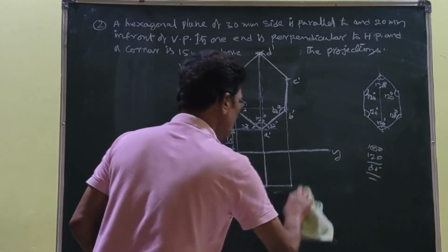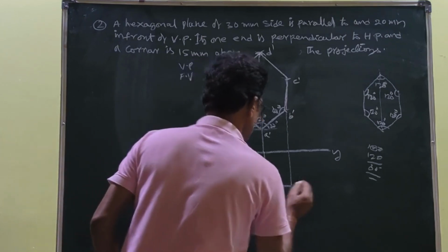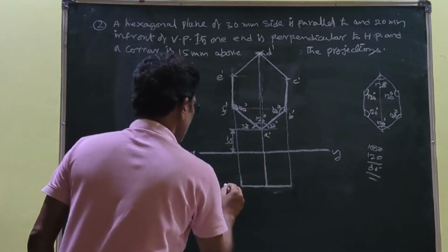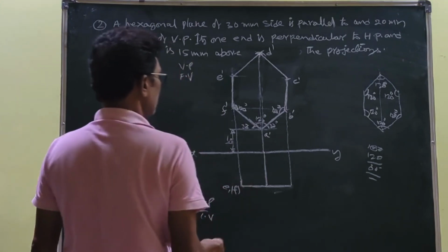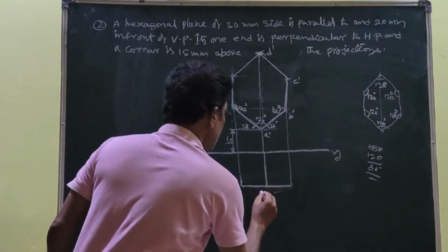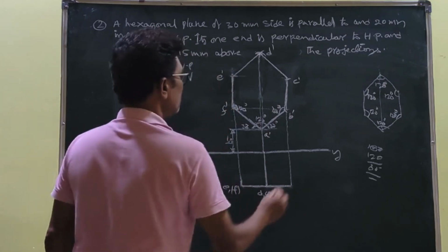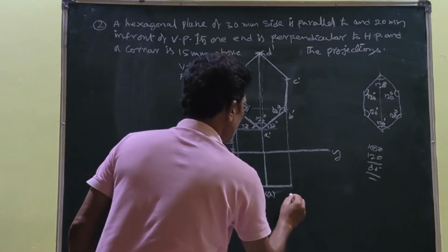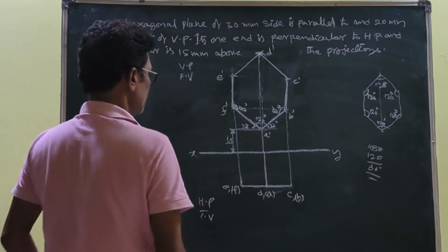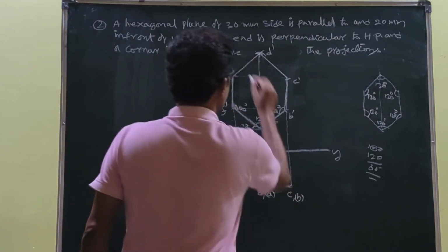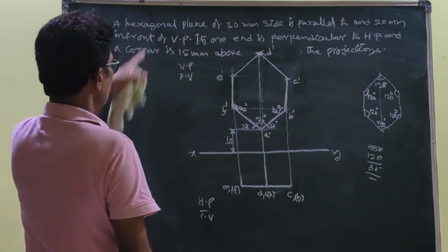So you can remove this one. This is the top view. Now the names. This is the visible E dash E, comma F, you put it in bracket if you want. Here D, top view, D is visible, A is put in bracket. Here C is visible, top view, C comma B, put it in bracket. Okay, this is the top view, this is the front view. Like this you have to construct the front view and top view of this given problem.